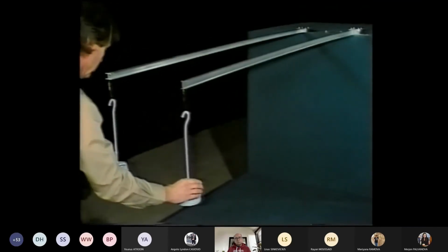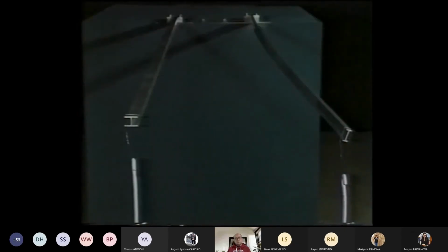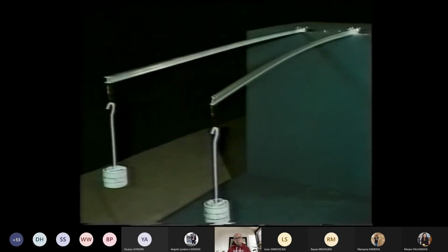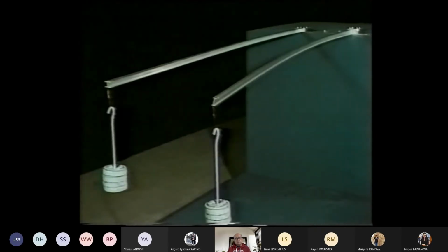Initially, as equal load is applied to each beam, their behaviors are almost identical. However, for the beam with low minor axis stiffness, as loading progresses, instability intervenes. The cantilever on the left does not suffer any instability and would eventually fail by plastic action.